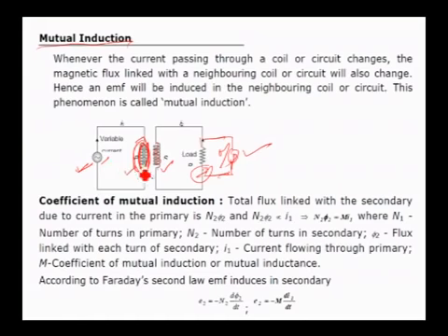As and when the current through the primary coil changes, there is a change in the secondary coil which will induce current here. That current will be indicated by the deflections in the galvanometer. You can use a voltmeter to measure the EMF induced. You can use a galvanometer to know the current direction.